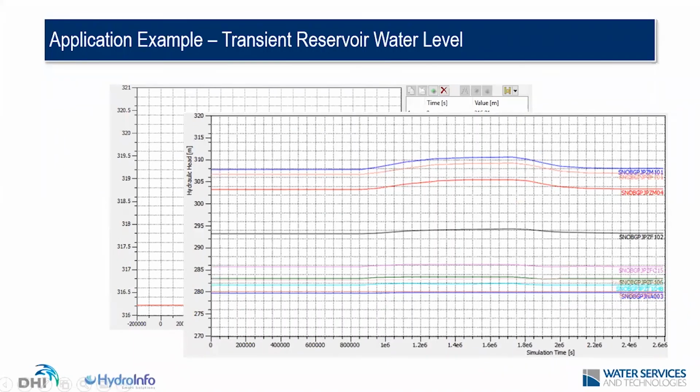And if we had transient observations, we would add in the observation wells, not as a single value, but also as a time series of the values observed in each well, and we can do a transient calibration, which is usually much more difficult than a steady state. So with that, we will finalize.